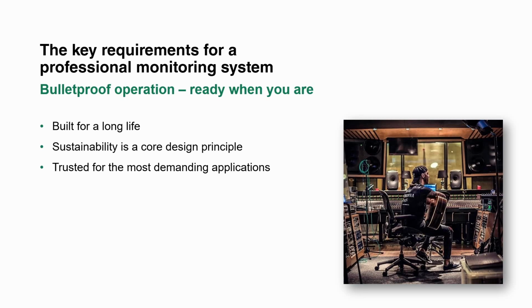In the vast majority of our products now, we employ intelligent signal sensing so that when our products aren't being used, they can go to sleep and again consume a negligible amount of energy. So in a lot of cases, less than 0.5 of a watt. Very useful for smaller systems, but when this is rolled out over larger facilities where we're talking about hundreds of loudspeakers, there's a significant element to cooling and powering systems, that the lower amount of energy that we can use, the better it is for the customer, for the facility, and ultimately the environment.